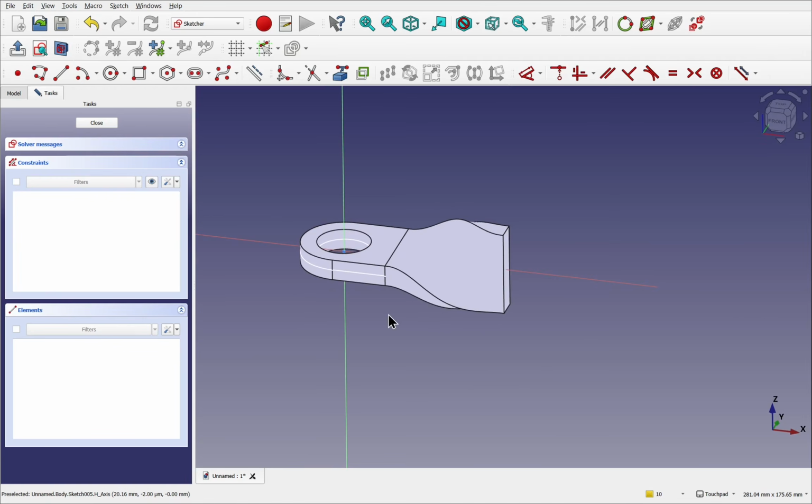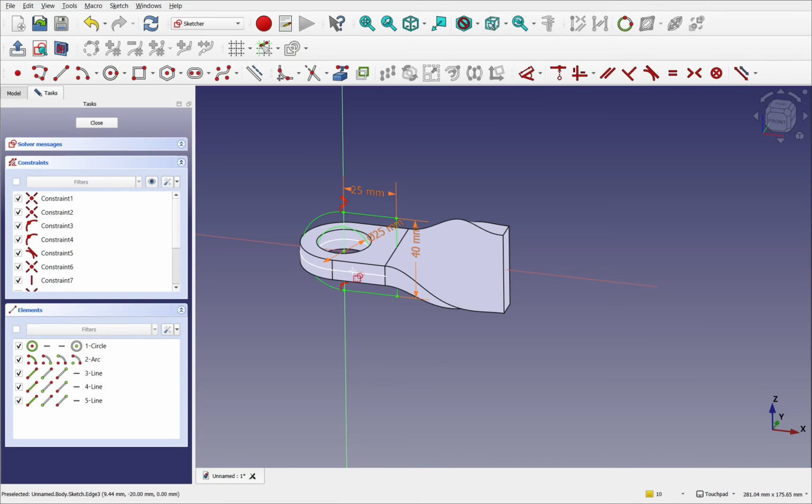I'm going to use the carbon copy now. Using the carbon copy tool, and we hover over this sketch. If we look down to the left, we get a message: Selected sketch is not parallel to this sketch. Hold Control plus Alt to allow non-parallel sketches. If I hold down Control and Alt on the keyboard, we can highlight this sketch now. If I click on it, it comes through.